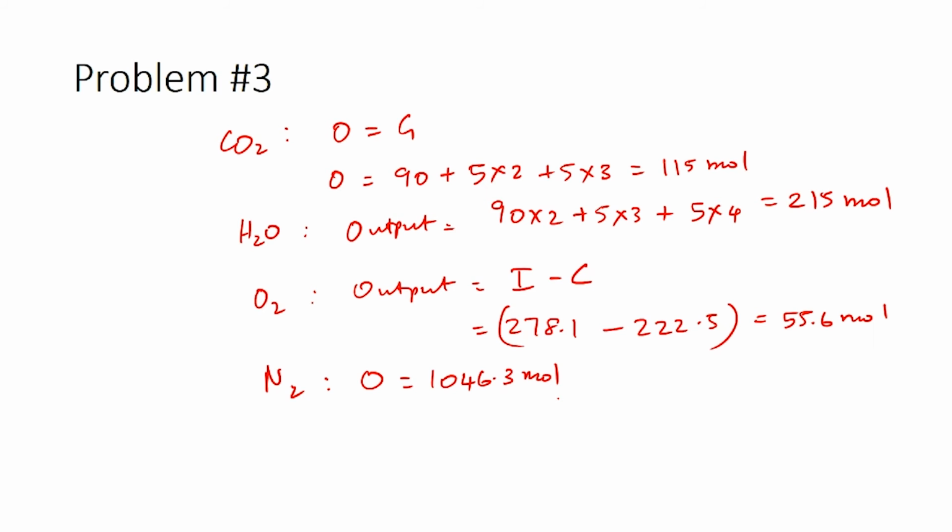We know that the stack gas is coming in at 1000 degrees Celsius. So, now our next step is to perform the energy balance calculations for the waste heat boiler. Since all these gases are combustion gases, we can use tables from the textbooks or reference books where we can get information about the enthalpies for these gases. Table B8 in Felder-Rousseau, which is one of the prescribed textbooks, has these values, and we can directly use them for performing these calculations.